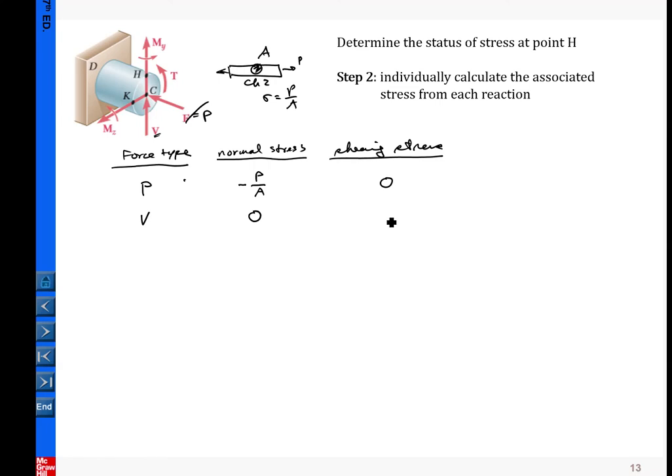And the shear stress, we know that is VQ over IT. This is the template here. So this is a cross section, and that is where the edge is located. And now V is pointing upward like this, and this is the centroid. So from here, you should right away identify first.